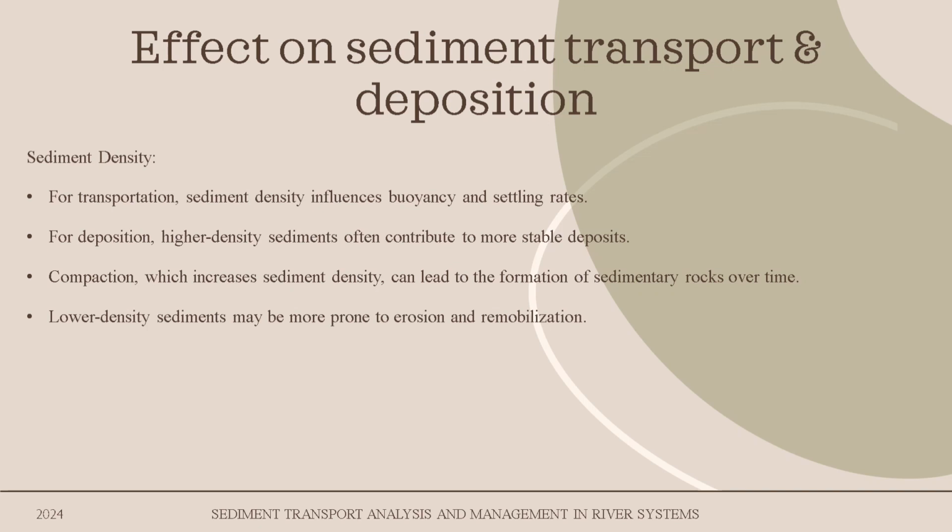For sediment density, for transportation, sediment density influences buoyancy and settling rate, where higher density particles settle faster in water, while lower density particles may remain in suspension longer. Compacted sediment with reduced pore space can also be more resistant to erosion.